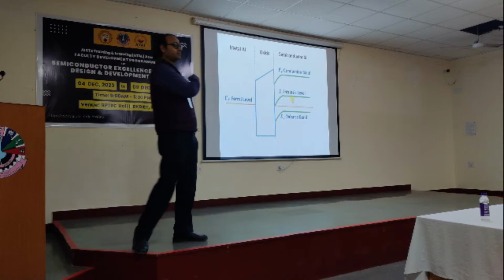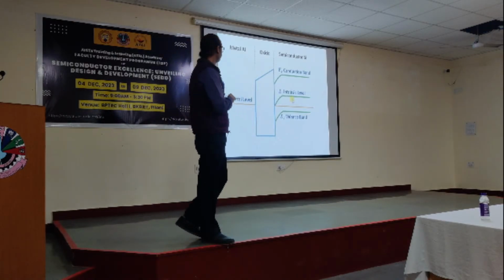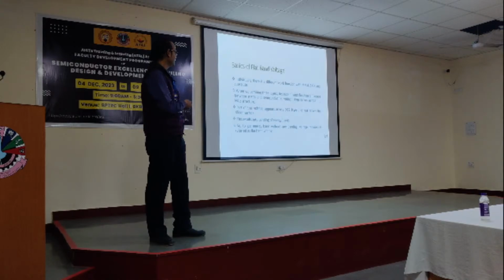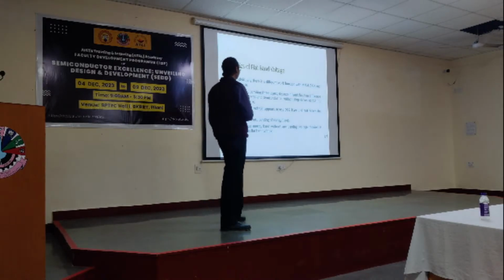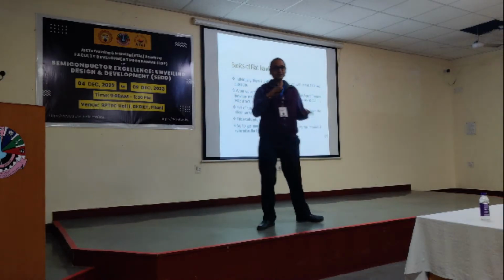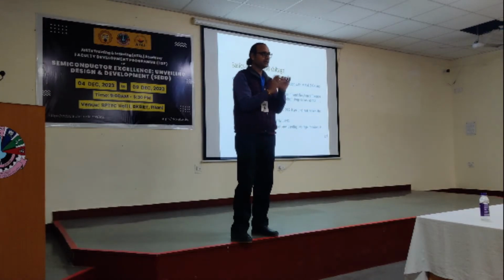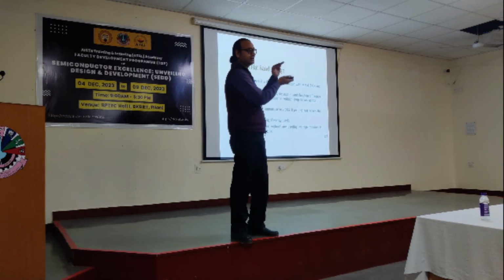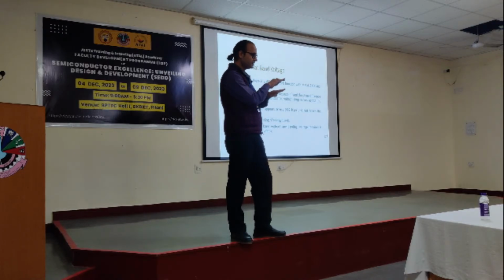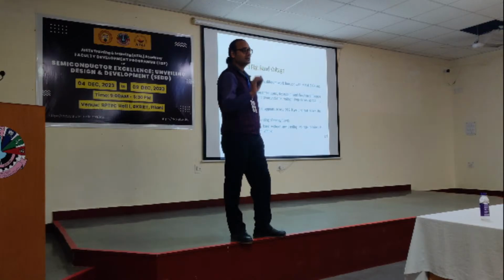This is the energy band diagram under that scenario, when the metal was aluminum with 4.1 electron volt, whatever that is. So we can have calculations for these. Again, as I said, flat band voltage is there, right? Just like his question, we have band bending depending upon the metal, bending upwards or bending downwards. So first we need to make it constant throughout. That condition we call flat band.